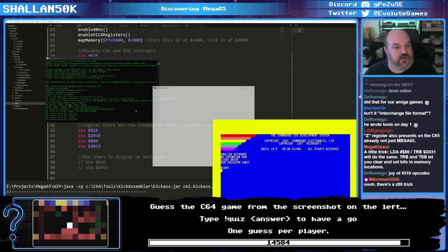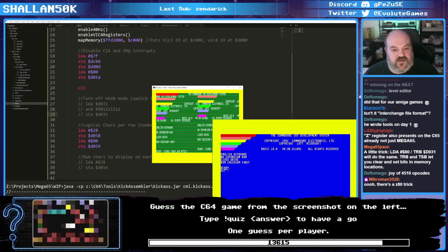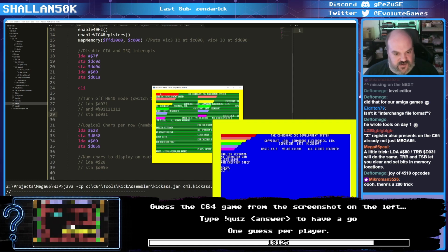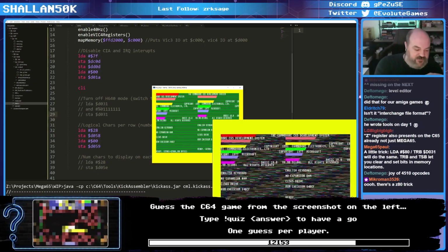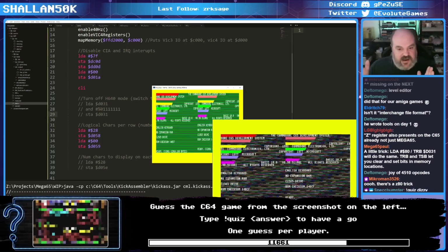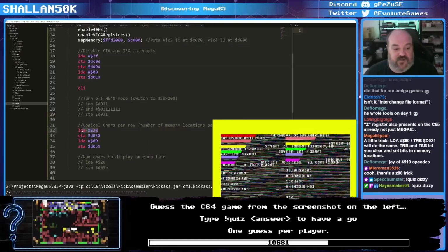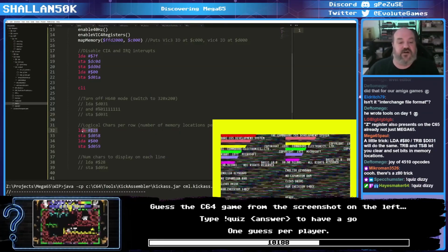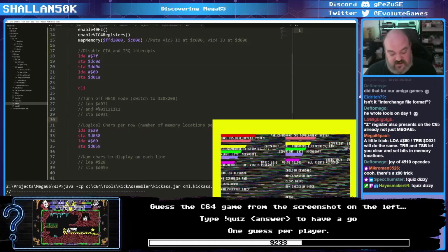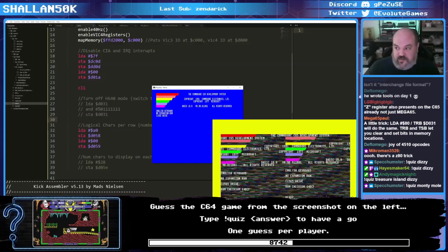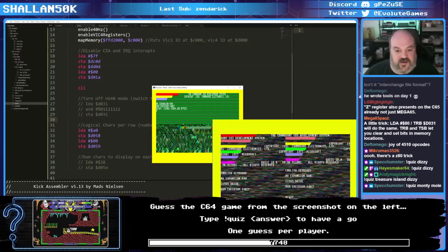So what will happen is now it's drawing this line, and it draws this line, and it's perfectly fine. But the next line is 40 characters long. It's not 80 characters long. The next line is 40 characters long, because I'm telling it that each row is logically 40 characters long. Likewise, if I double that, so if I put it up to 160, it's going to skip lines, because it's going to display 80 characters and then it's going to skip. So you can see I've compressed what's here.